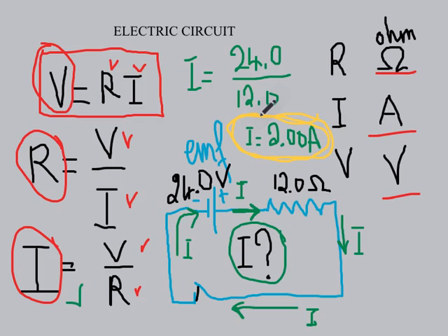So that's to make sure that you understand how to use Ohm's law. Ohm's law is about three parameters: the voltage of the EMF, the electromotive force; the resistance of the resistor, which is represented by the zigzag sign here, which we have seen in the previous part of studying the components; and I, the electric current. You don't show I in a circuit. I is the flow of electrons inside the circuit.